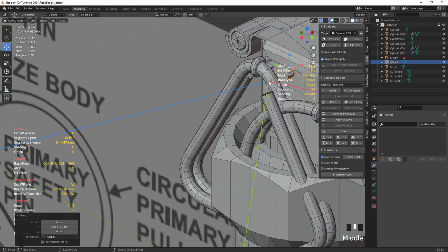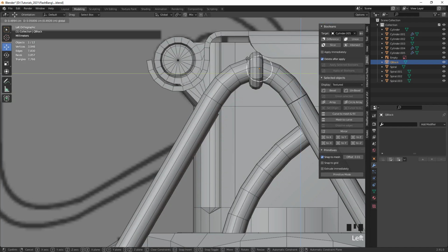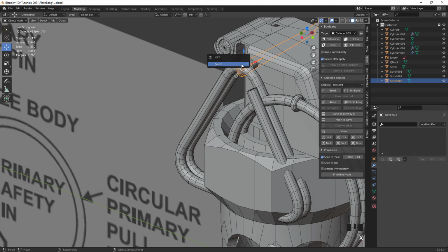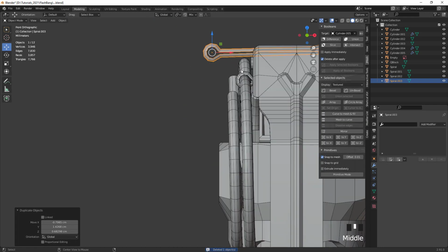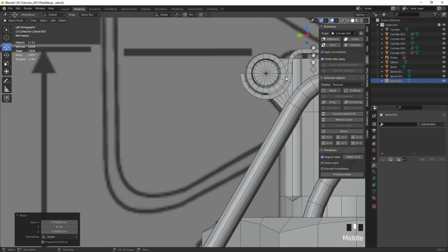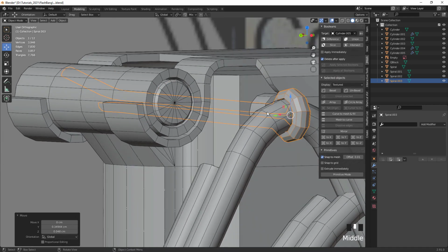Draw that onto the other object. And then we also need to cut a hole into this existing element here in the background. I'm just gonna delete that pin and copy the other one because we already did some changes on that one, which we also need on that one here. So just copying that back into place here.